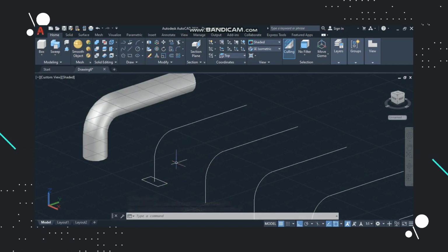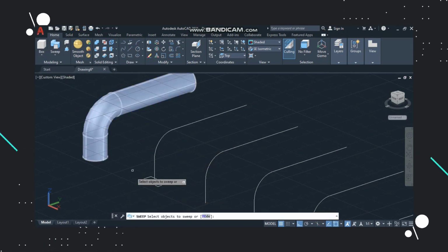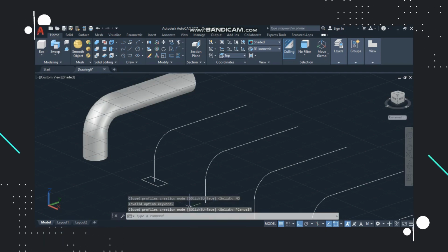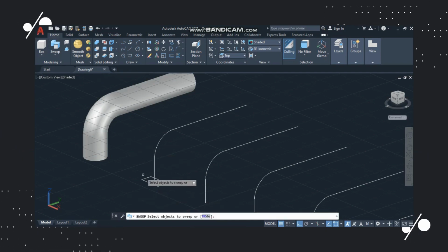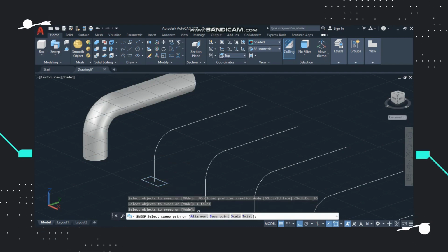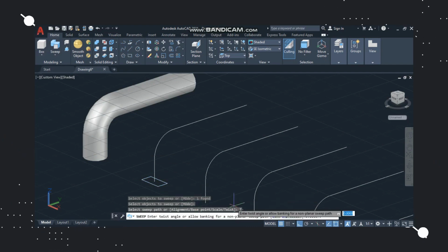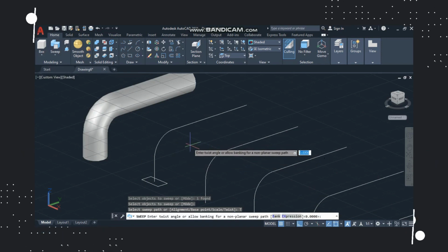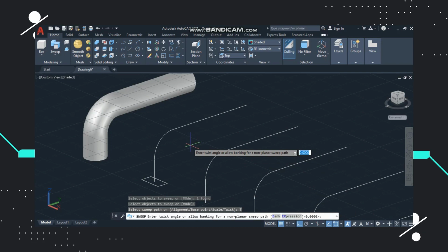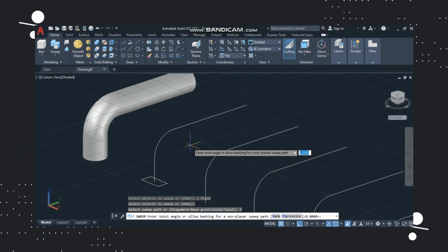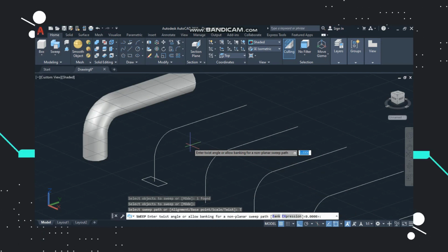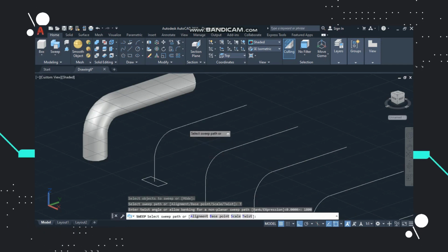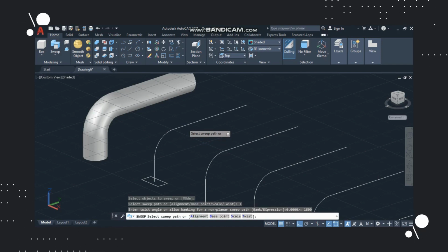As we created and connected the rectangle element, we will use the sweep command. We will use another feature of the said command. It is called twist, and this one allows us to create twisted 3D figures. From these sweep options, select the twist. Here, we need to specify twist angle, and be reminded that 360 degrees is equivalent to one twist turn. After you specify the twist angle, press enter to select the sweep path. Select the line element, then press enter, and you will see this figure here.